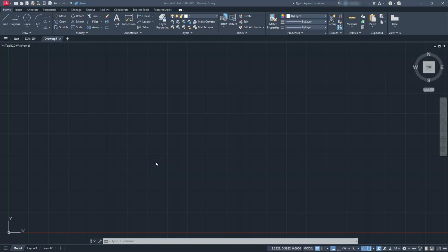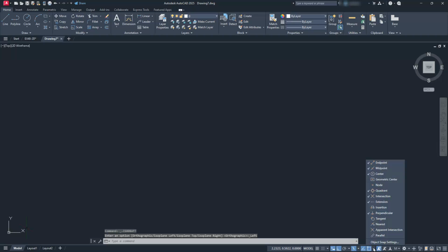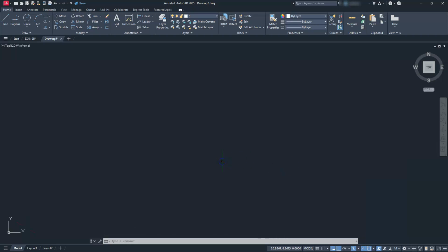Okay, so before we get started, let's go ahead and take care of some regular housekeeping that we normally do. We start off by turning off this grid. I'll go ahead and turn on the ortho. Since we're only working in the isometric, I'll go ahead and turn the ISO drafting on right now by selecting this icon here. And then we're going to take a look at what are my running O-snaps that I'll be using for this video. Okay, now we got everything set up.